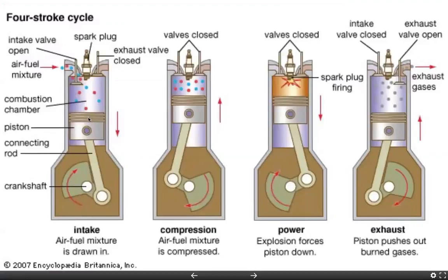And here's a piston. The exhaust valve in this case is closed. You have a spark plug, which we'll come to in a second, and that's the intake valve, which will close in a second. The piston, of course, is connected to the engine here, shown as a crankshaft and so on. Not so important for us. The next step is the compression. Then this thing turns, and the piston compresses the gas, and all the valves are closed. Nothing can escape, so the gas is simply compressed.